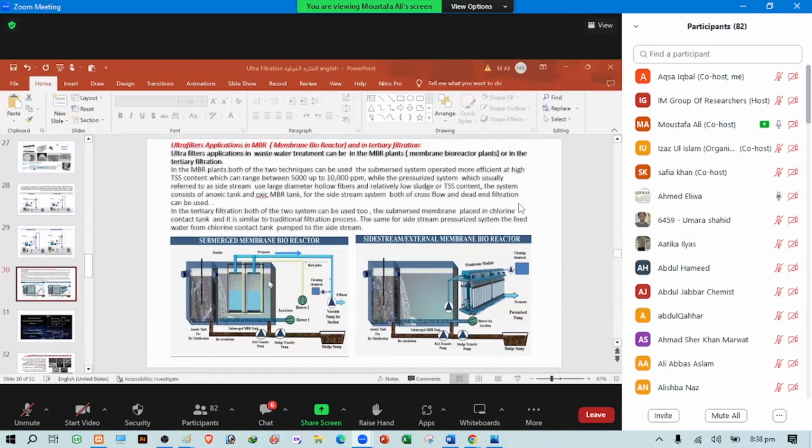Right, doctor, it's clear. It's crystal clear. Thank you. Yes, okay. So we are using one set of pumps for backwash and for operation, and we can just play with the valves to close in one direction and open in another. One sucks from the membrane and pumps to the tank, and one pumps to the filter in the opposite direction. So we can just handle it like that.